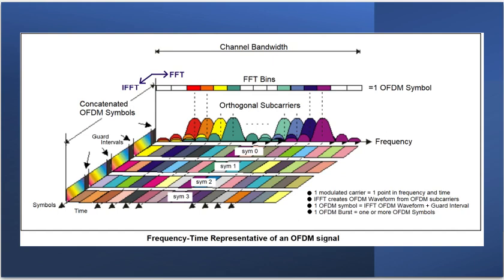So that's a problem with OFDM. It's always been a problem for cell phones and everything else, and it's going to be a particular problem for the broadcast industry, where they're trying to achieve 50 kilowatts or less, so serious power. The amplifier companies, like Rohde & Schwarz, have some tricks up their sleeve to help with all this, but that is one of the significant problems with OFDM. It helps with multipath, but the problem is mainly for the amplifier. You have to work in the extreme linear range.